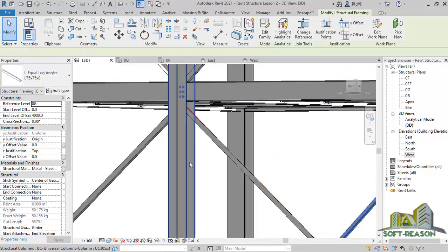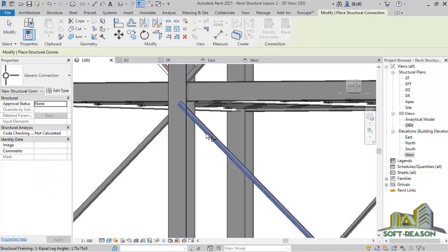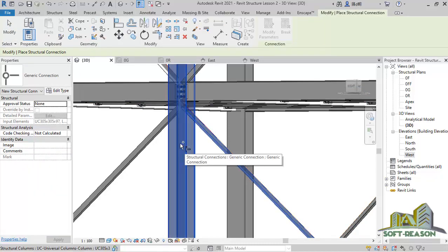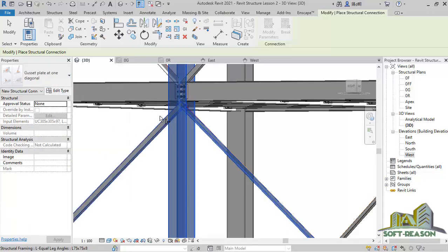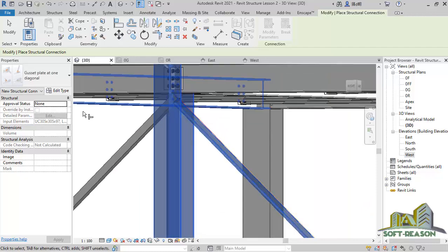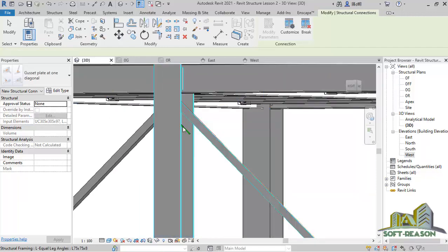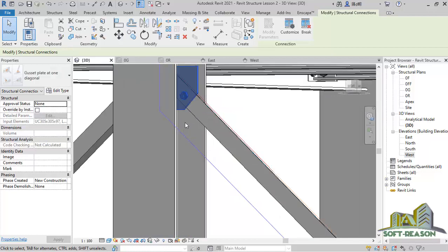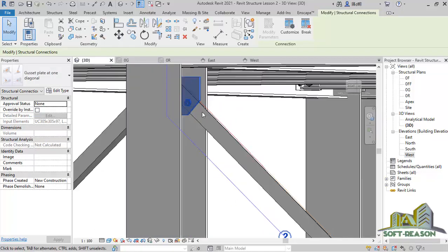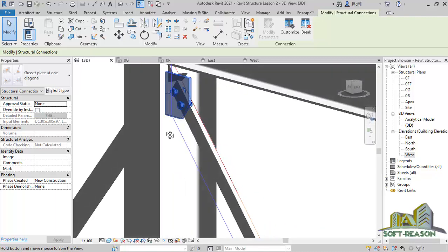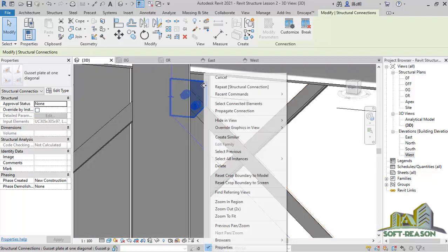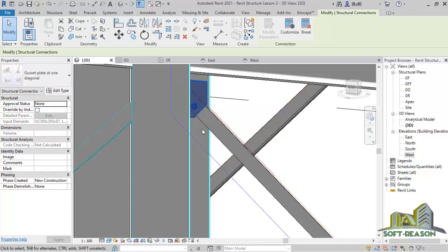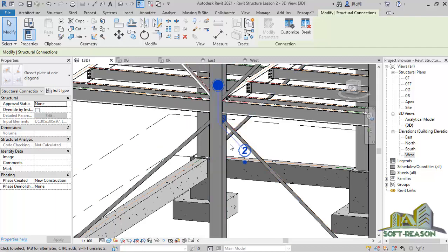Having this done like this, you just have to go straight to the connections, pick this, hold the control key, pick that, and then use these same connections for that place. Sorry, I did not place the instance at first. I click on finish selections to have that. Okay, so once you have that, you can see the connection is inserted successfully. Alright, so this is how it looks. Okay, so you can decide to just go by this. If you click on this and then you propagate it, you'll be having it on this other side.